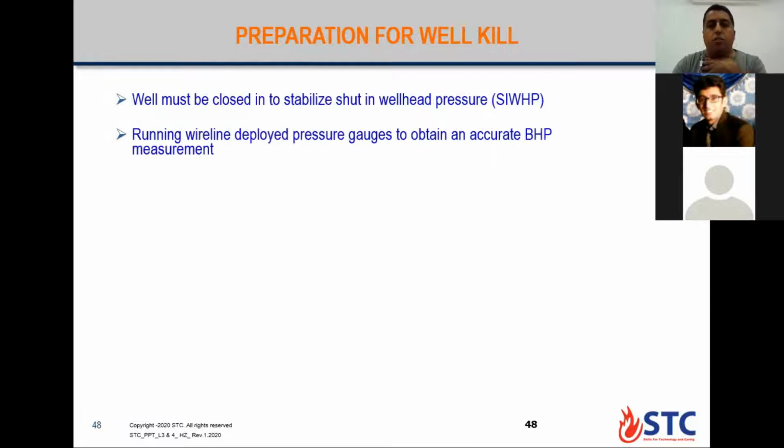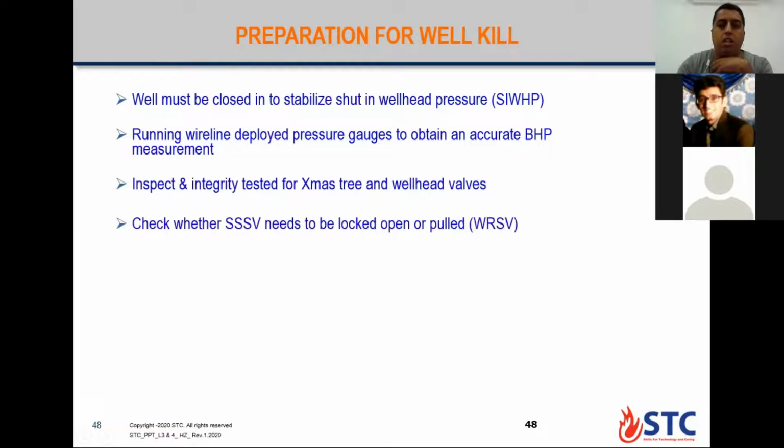Second thing, if you are going to run any slick line deployment pressure gauge to get accurate data about the bottom hole pressure or the formation pressure, we need to check, inspect and pressure test the Christmas tree and wellhead valves to make sure they are holding the pressure and there are no leaks, especially if you're working with a gas well or high percentage of H2S.